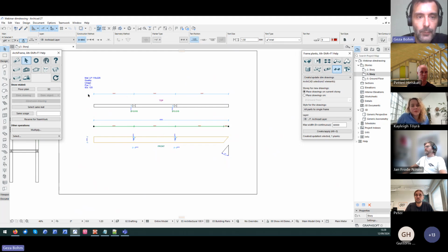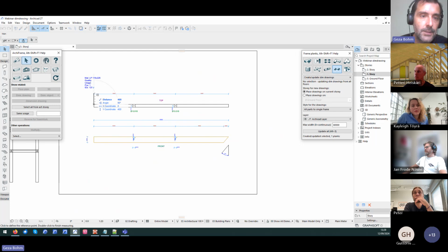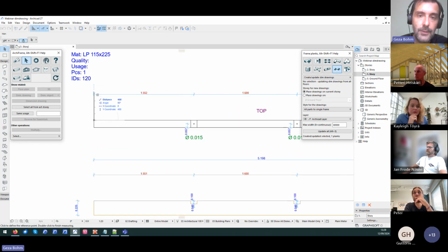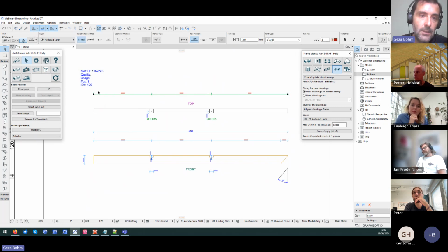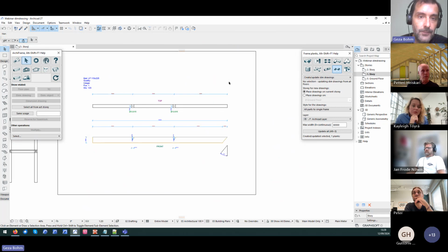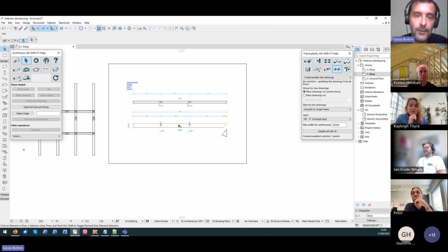You can see that the other projection, the top, also kept that bigger distance. So this is redrawn too, because it's another main machining. It's for the top projection. It can be that the main machining line for the front projection is different than main machining from the top projection. In this case, for this plank, it's the same, but it can be different. If the machining is not visible from the front, then it will be missing from here and only shown on the top.